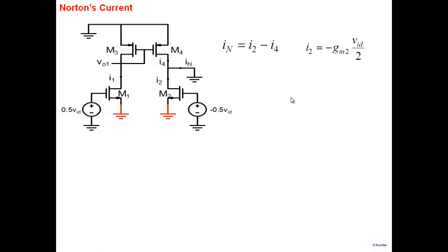And the way we do it is, I2 now, note, if I look at this particular circuit, this one is ground here, and there's a voltage attached to the gate here. And note that when you look at a transistor from the drain side, what do you see? You see a current source in parallel with R0. What is the value of the current source?